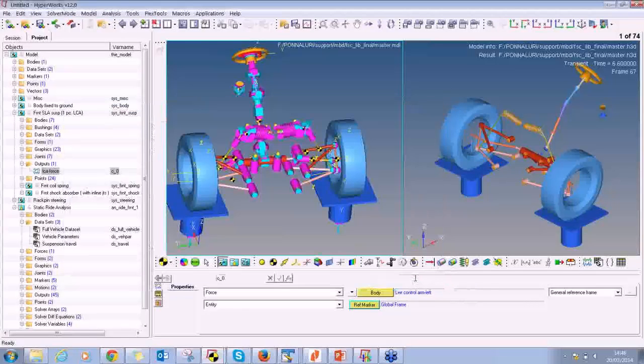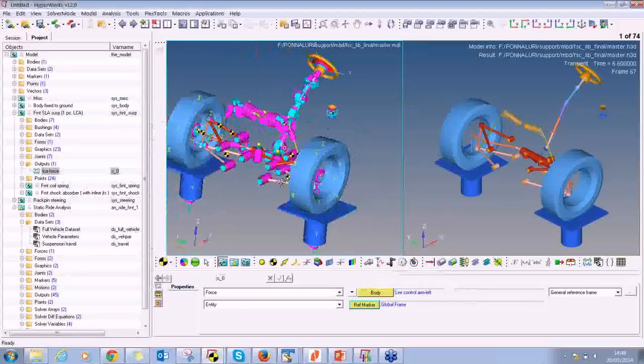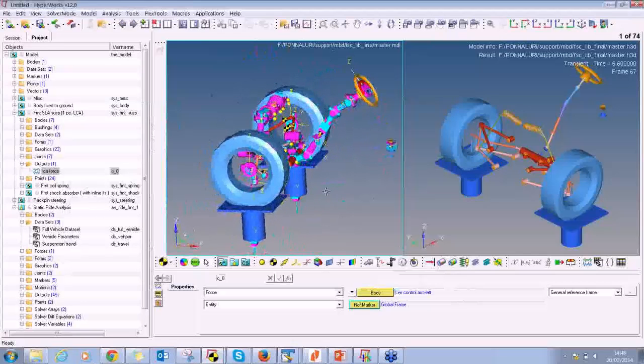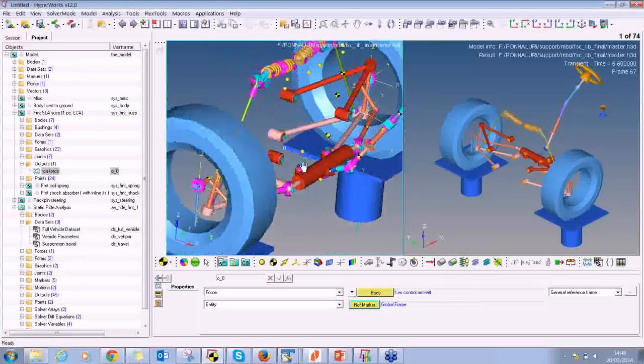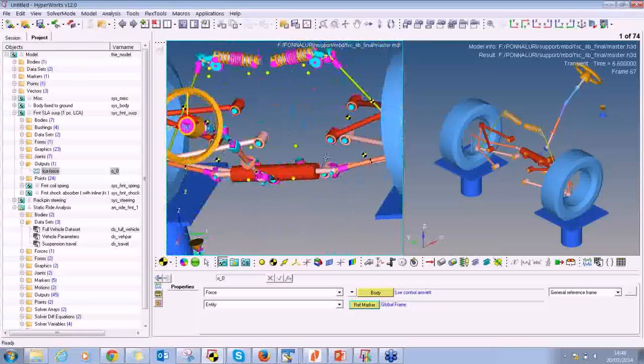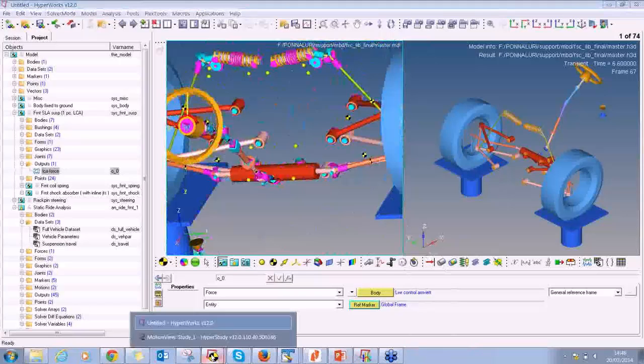Why am I not selecting the x coordinate? X is by definition along the length of the car, so I don't want to reposition these points in the x direction. I want them to vary in the YZ plane, so I am selecting just the y and z coordinates.